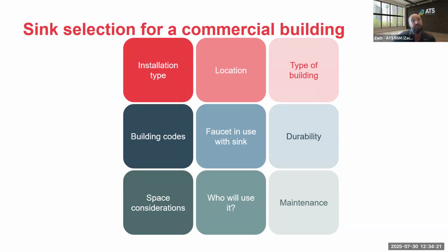They have a certain amount of durability that they can handle that, but temperature shock is certainly something that can crack a terrazzo or molded stone mop sink, whereas stainless steel is going to handle that a little bit better. It's a lighter material as well comparatively, but I think the budget friendly economical applications might be more focused on the molded stone or terrazzo, although those are certainly starting to meet in the middle depending on the price of steel at the time.